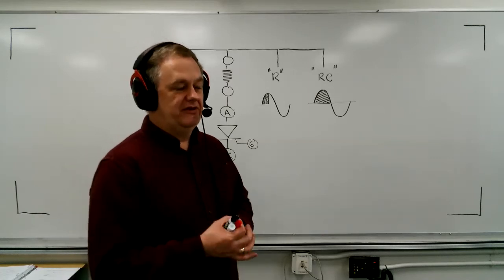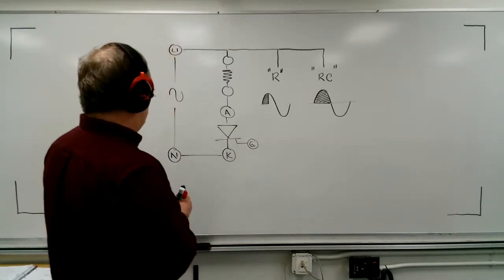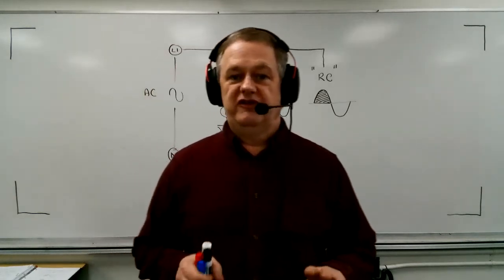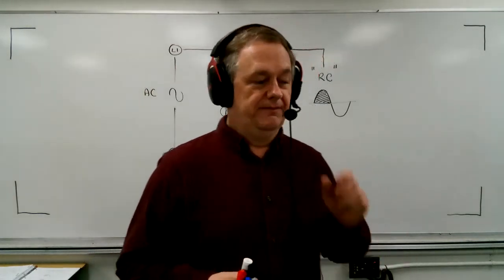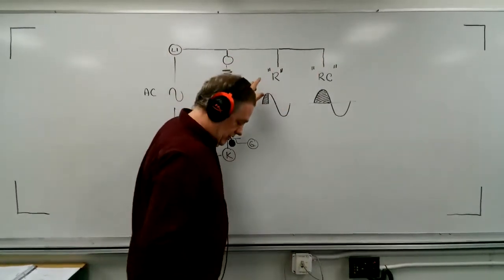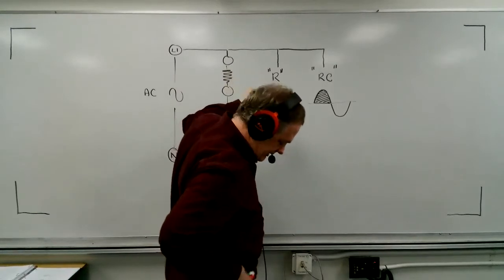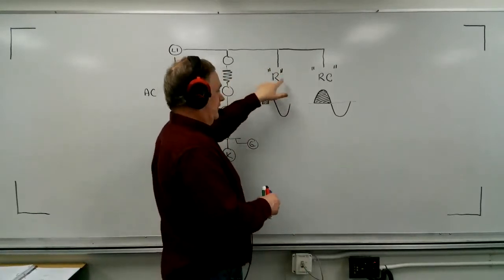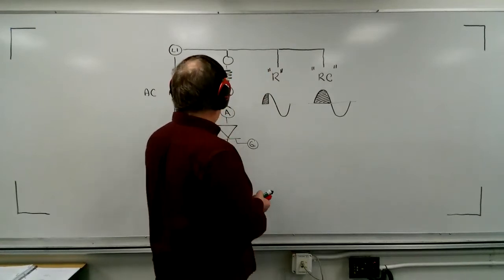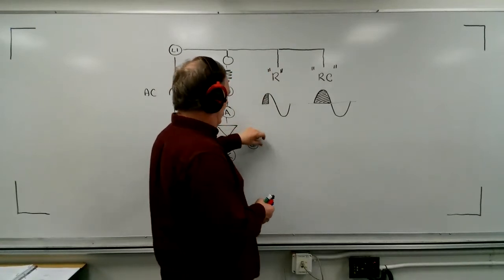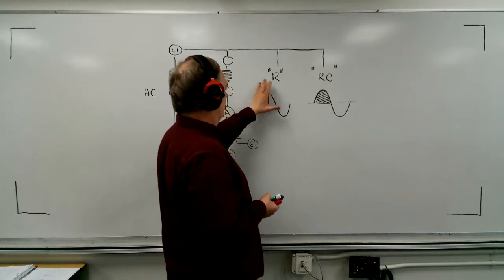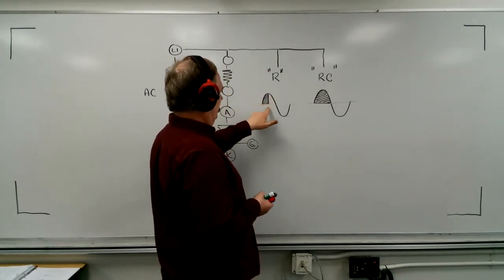So the next thing that I need to show you is, up to now we've been talking about a resistance only triggering circuit, and that means that in the trigger circuit all we use is a resistor. In this case, of course, we would have that gate protection diode, but essentially the only component controlling the current really is resistance.